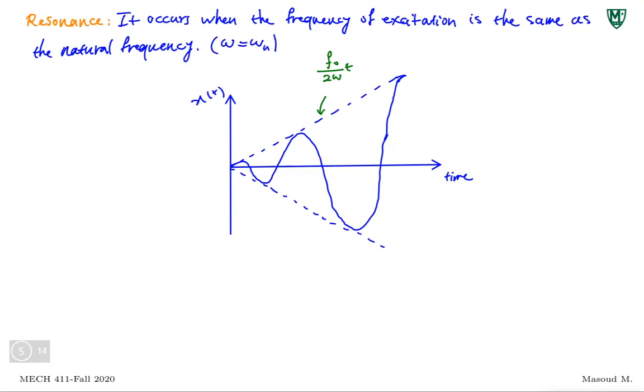Replace critical speed and operation speed with natural frequency and frequency of the excitation. These are the same, just different terms. That's why you always design a shaft to make sure that critical speed is not close to the speed of the operation. It's the same concept, resonance. You want to avoid resonance, because if you do, then the shaft starts bending up and down hugely.